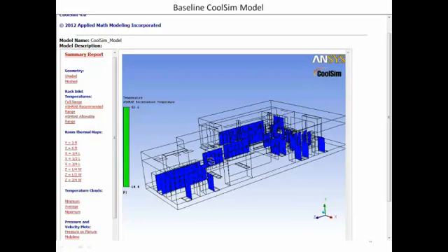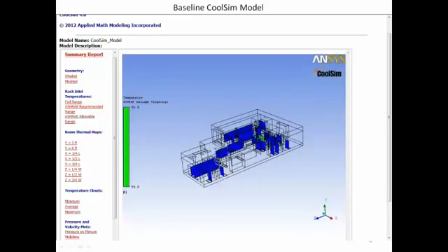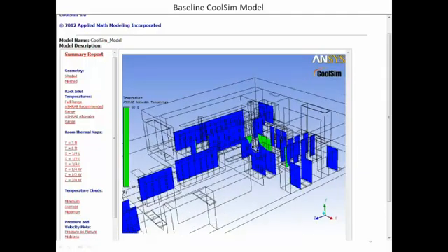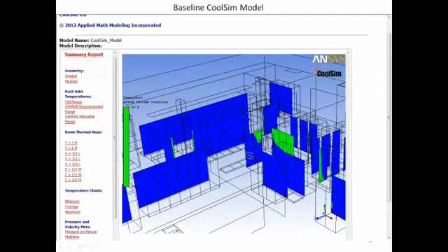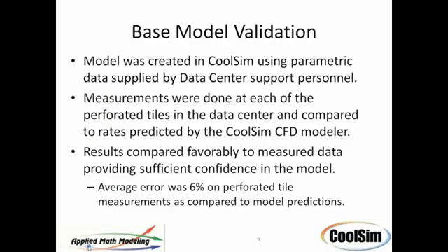So what you see here is that this data center is way below the recommended inlet temperatures for Class I standards. It's simply too cold. Now, the allowable is a little beyond that. The allowable goes to 59 degrees, and you see there is one rack in the room way up here that is somewhere near specification. But other than that, we're way out. So the room with 4 CRACs on is just way too much air and way too cold.